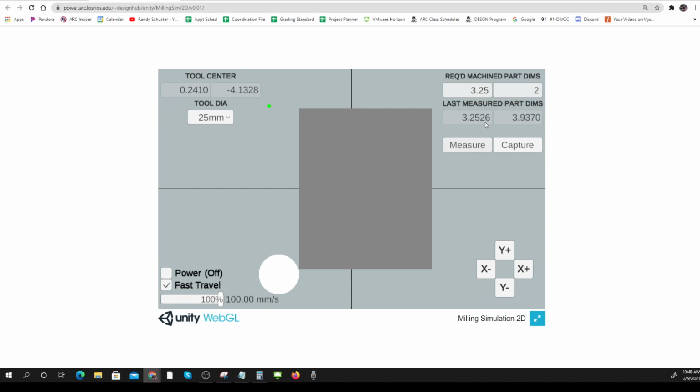Just the way I've got, where I am and what I've got and my measurements and the size of my cutter. That's still not too bad. 2.5 thousandths. Most machine tools right now will cut within 1/1000th. Okay, but you can see my tool cutter isn't perfectly round. But I got a pretty good part.